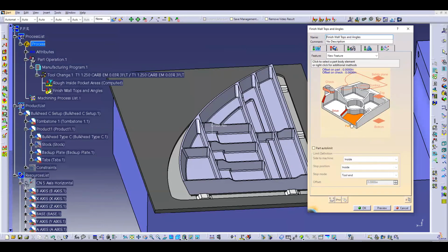What this does, I define a part. By the way, I don't know if you noticed it on the previous one, there's always 5 tabs across the top here. These tabs always represent the same type of operation in any operation you're in. So the information underneath these tabs is going to be the same type of information in every single operation you pick. This tab here we're in is always going to be our geometry selection.